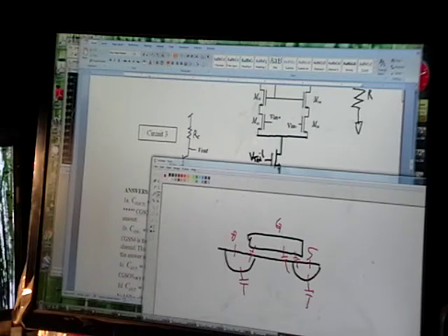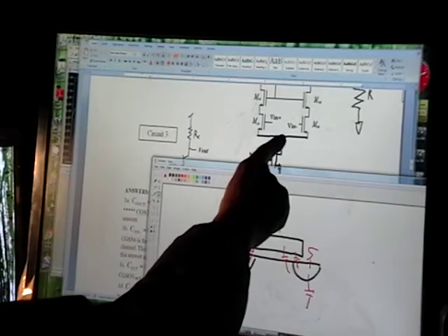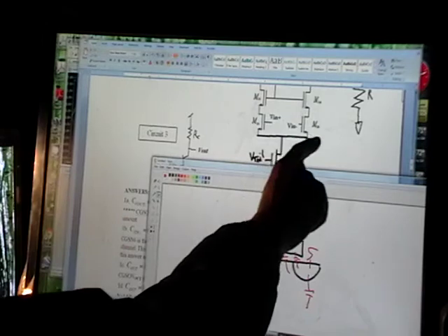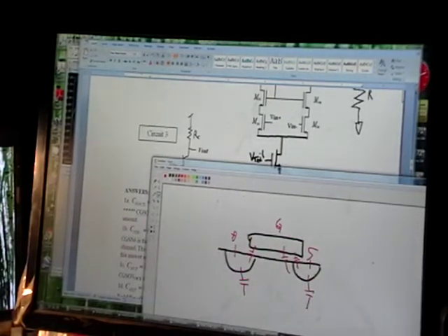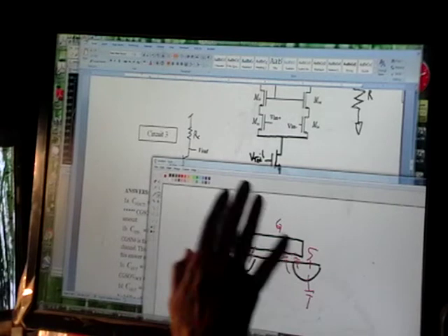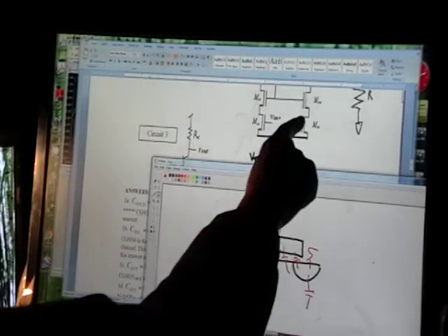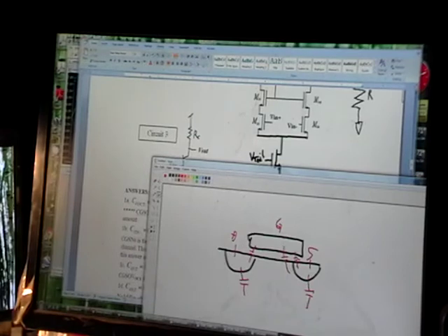You know, if this circuit is a differential circuit, this node right here isn't moving. So any capacitances to the source, those are just whatever they are. Okay, so gate source is whatever these capacitances, their values. There's nothing you have to do with them. It's like the other side of them are connected to ground. So that's just the value. Okay, now this gate drain capacitance, that's something else. This is in the cascoded case.